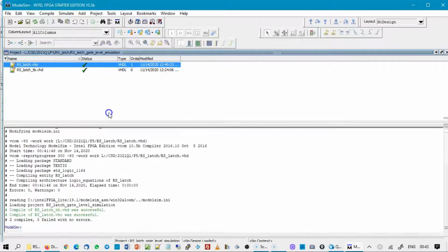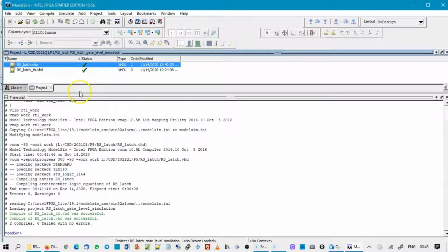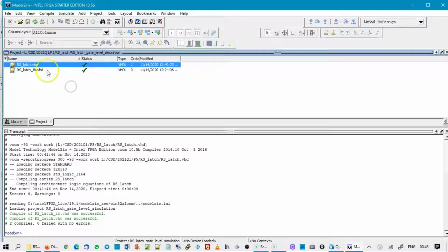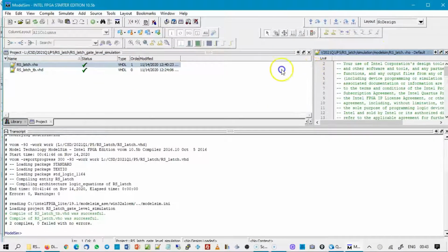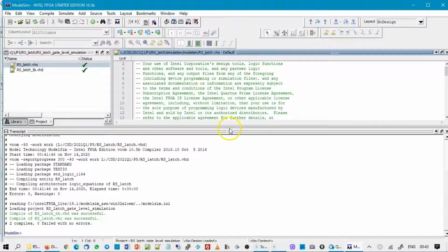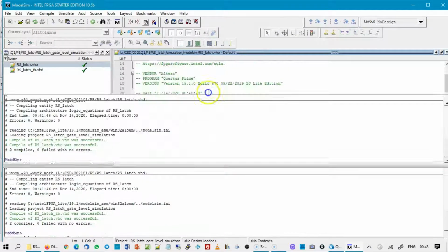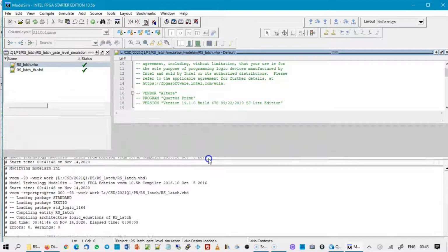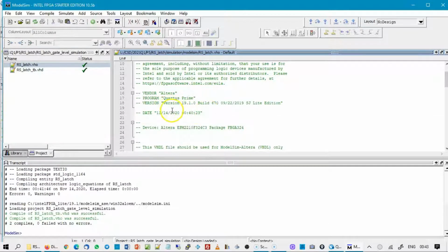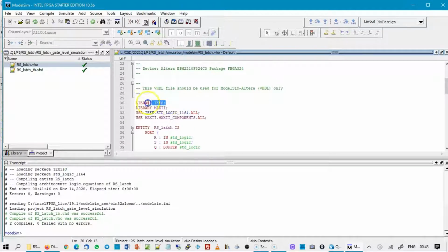And this is what we have to simulate now. All right, if you like, you can keep an eye on the VHO. It is like this. You see a file that now has extra libraries to define the chip very well, to model the chip very well. You see, you have this MAX2 library because it belongs to the target chip.